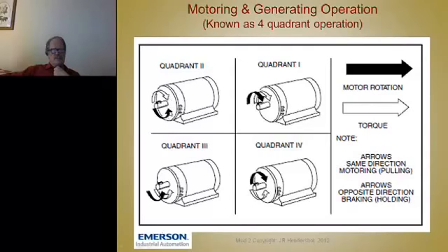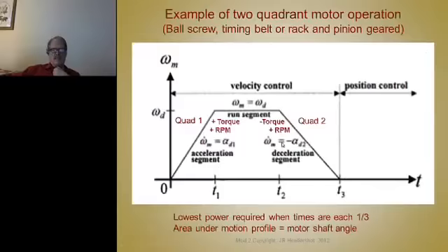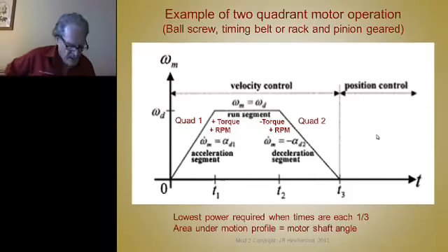Quadrant 2, when you're braking, you've got clockwise speed, but you've got counterclockwise torque. So that's kind of handy. It's good to have this thought in your mind. These are concepts that need to be in the back of your mind before you design a motor. In my opinion, they're more important than how the inverter guy is going to drive your motor. You need to know a little bit about that, but not nearly as much as he does.